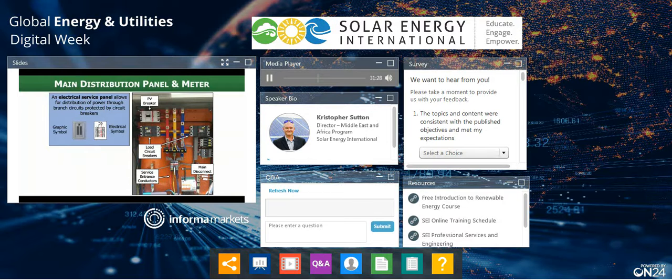Now, when we take the output of that system and connect it into the grid, this is just showing a couple of photos, and understanding that we're measuring things with our meters, and we're using electrical service or electrical distribution panels to move all this energy and interconnect together. This is just a photo of the inside of an AC residential electrical distribution panel. The service entrance of the utility conductors are coming in from the bottom. There's a main disconnect right there, or a main isolator.